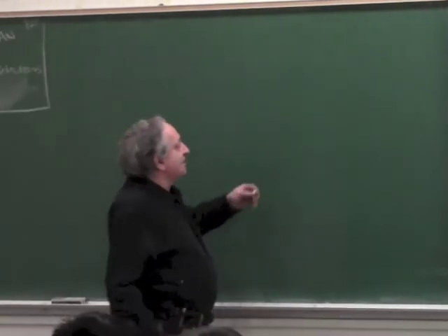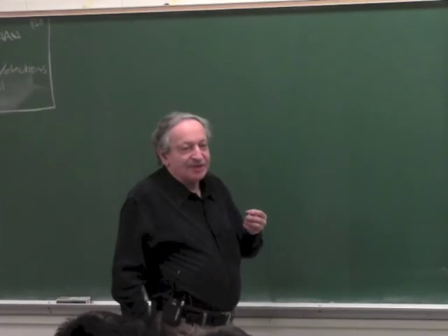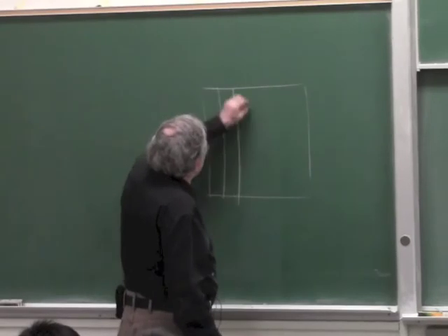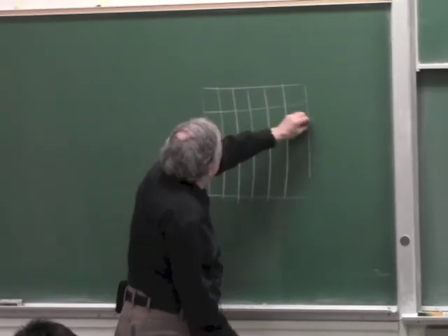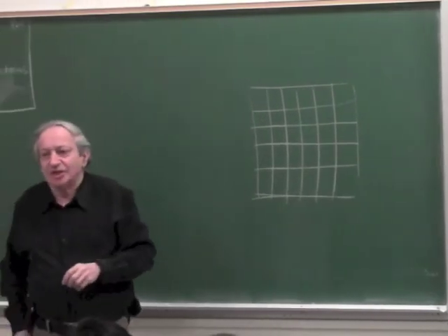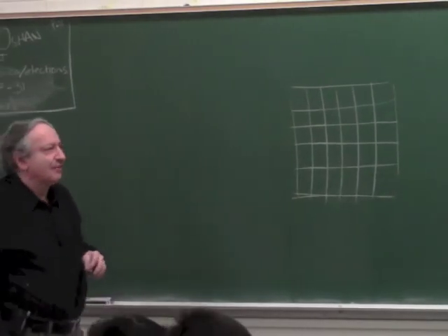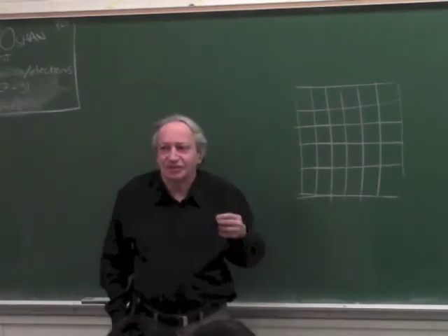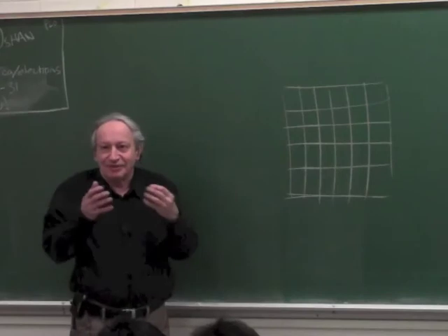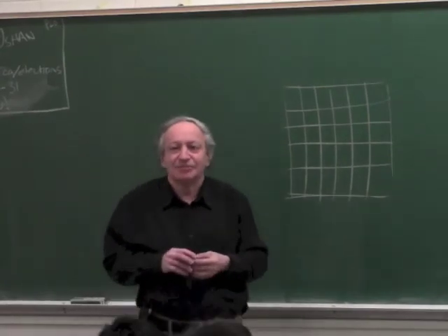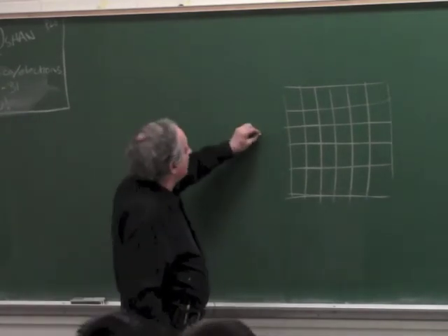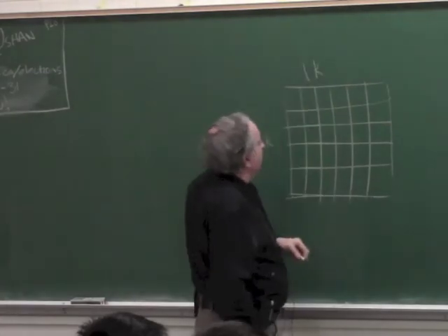So let's just think about a few basic things about using a camera as a sensor. The camera is a grid of sensors. The old cameras were CCD, charge coupled devices. There are a lot of cameras now which are CMOS, which is an easier thing to fabricate, and it's also compatible with the processing. So you can fabricate on one wafer the camera and all the processing electronics. But this really doesn't matter. That's for electronics engineers. What matters to you is that it's an array, typically 1K by 1K.